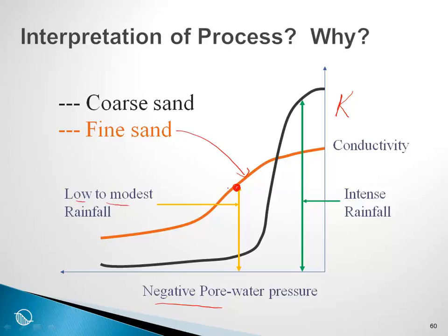and in this particular case here, the conductivity of the fine sand, of course, is much higher than that of the coarse material, and therefore the flow goes where the least energy is required. In this case, it goes through the fine material because it has the capacity to carry water with less energy than does the coarse material.